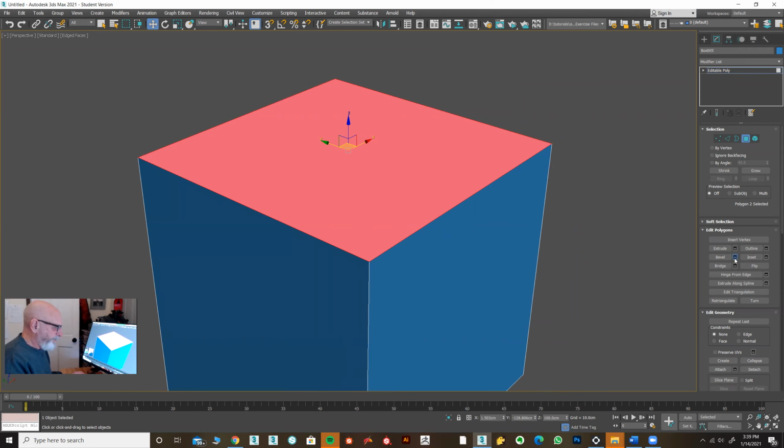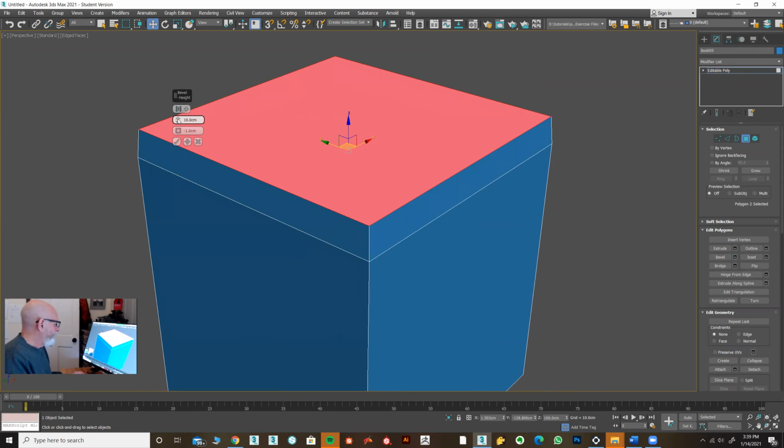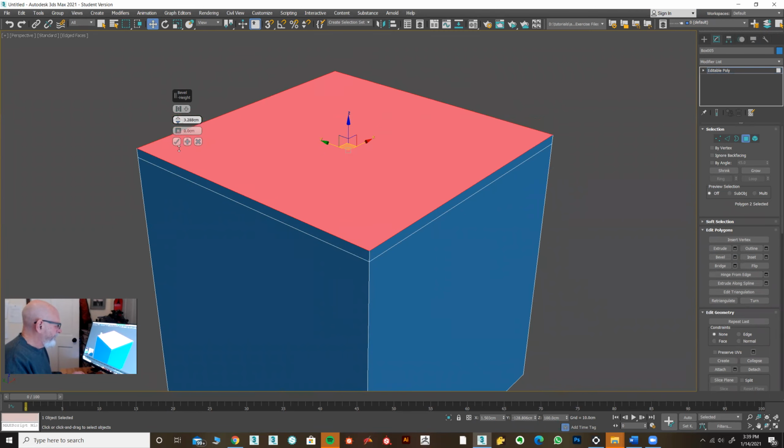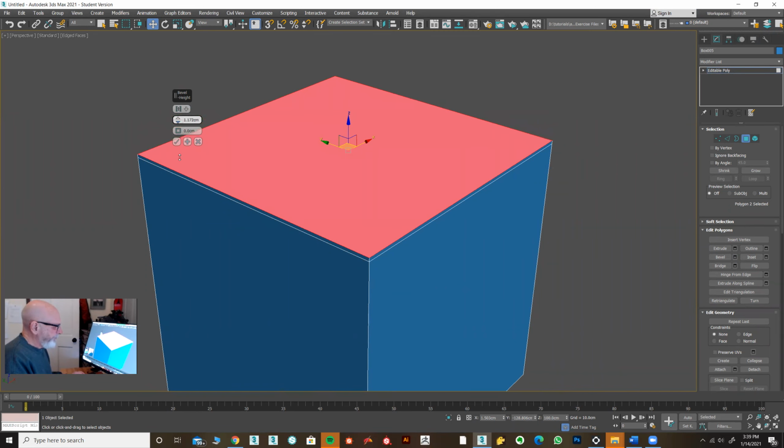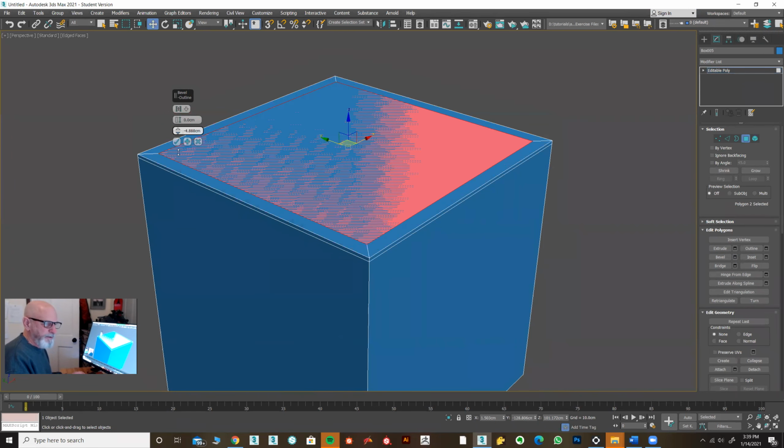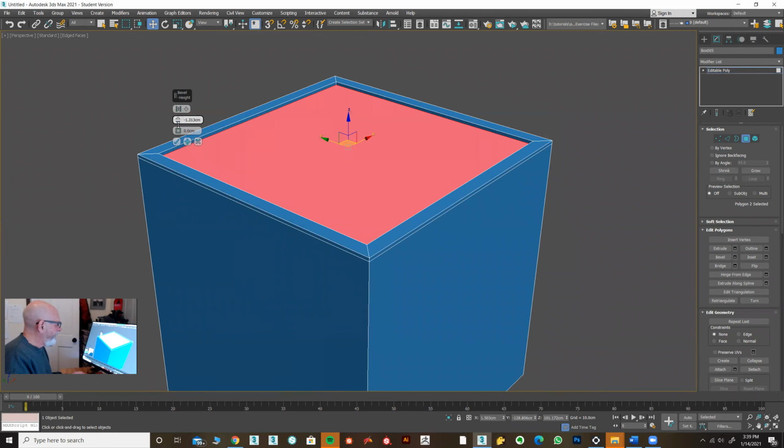So I'm going to use bevel. So no outline. Up a little tiny bit like that. I think that's how it is. Hit the plus. No height on the next one, but bring this one in. Hit the plus. No outline on this one, but come down a hair. Okay, I'm dragging right on the spinner most of the time. Okay, so that's the top.